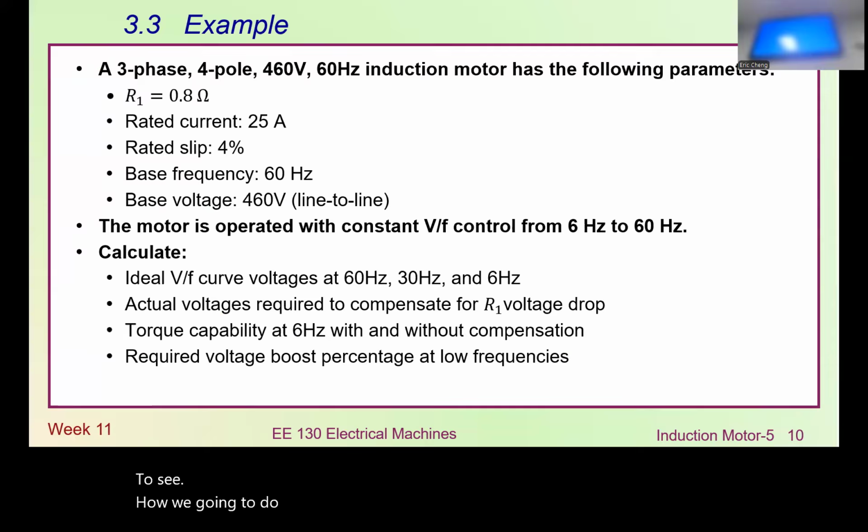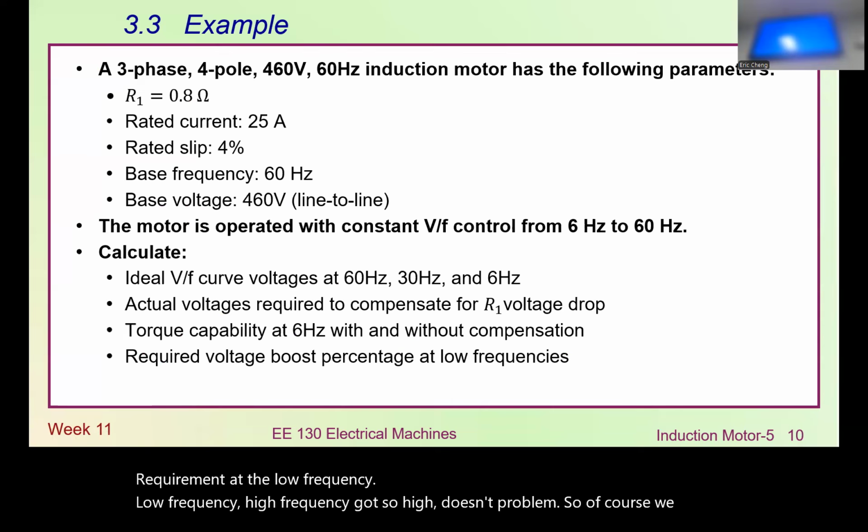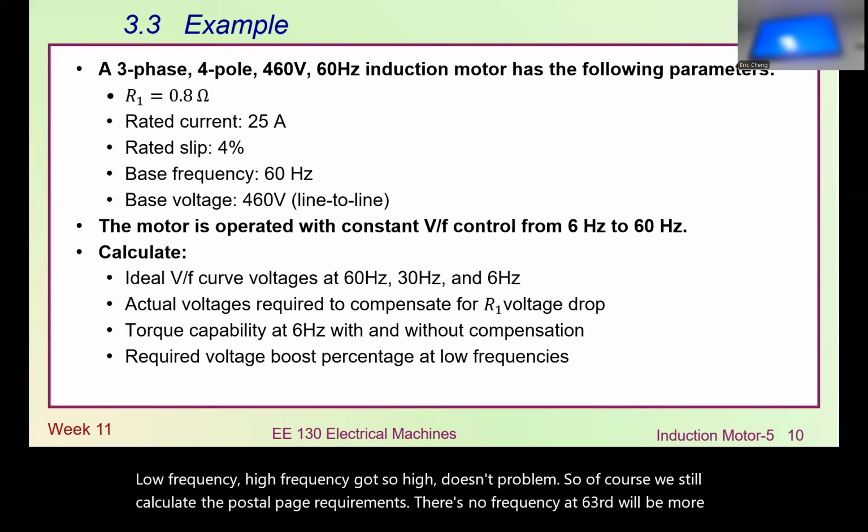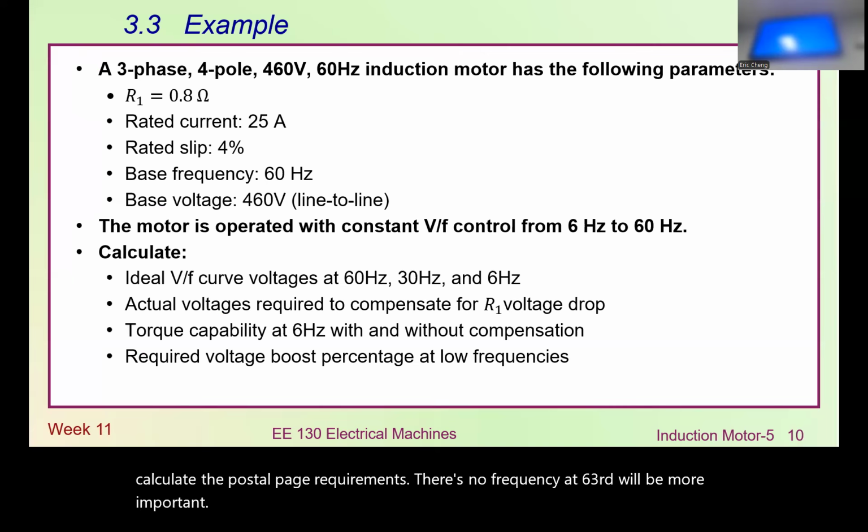So if we go for this one, we first need to calculate the boost voltage, the required voltage at low frequency. Usually boost voltage is important at low frequency. At high frequency, high voltage doesn't bother us. So of course we are still calculating boost voltage requirements, but low frequency will be more important than 60 Hz, without that compensation. That compensation means the boost voltage.